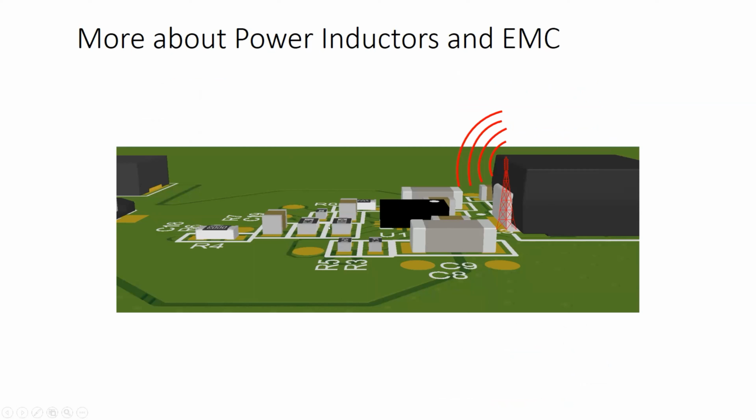And this is actually a design we'll take a look at tomorrow, where I've replaced this inductor in the 3D model, but this is not the inductor we use. And there are trade-offs that you're going to make, right? You can easily optically inspect this inductor. Other inductors you may not, but it might not be the best fit for your design depending on the size and other design constraints you have.